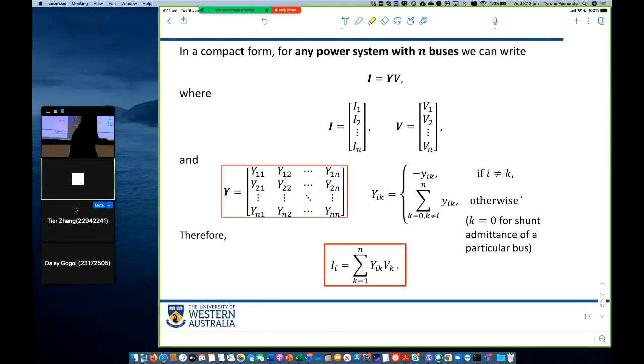And the equation in the middle row, right hand side, tells you how to actually obtain those elements in the admittance matrix. So it says the element uppercase Yik is equal to negative lowercase yik, because you take the admittance of the line and you negate it. Remember I said that. And then when i equals k, we are looking at the diagonal elements and you simply sum the admittances of all the lines. So that's what you see there, right?